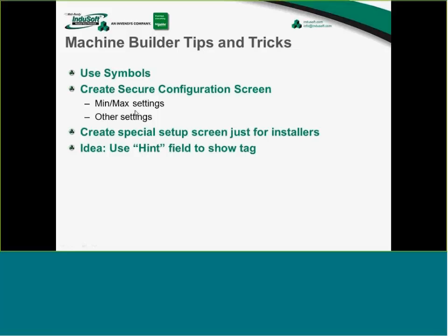To give you an example, I worked many years ago on an InduSoft application where we actually took over 50 different InduSoft applications and converted them down into a single application by putting minimum and maximum and set points on a single configuration screen. So allow the maintenance people or the setup people to do that, and allow one application so you only have to maintain one and back up one and archive one.